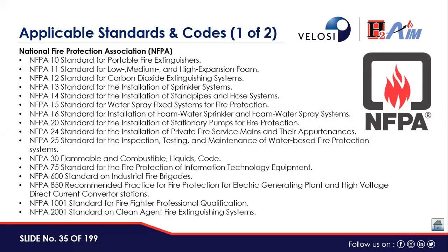Various kinds of standards are available for fire protection, but the most commonly used in the industry is NFPA, the National Fire Protection Association of America, which has various standards used for various activities of the fire protection system. For example, NFPA 10 is for portable fire extinguishers, for daily use. Then NFPA 11 is for low, medium, and high expansion foam systems.